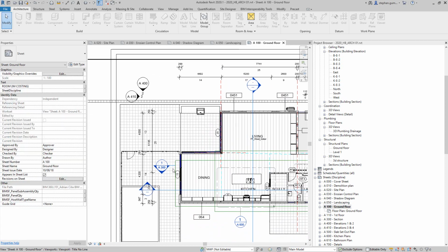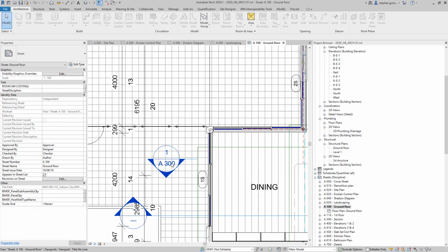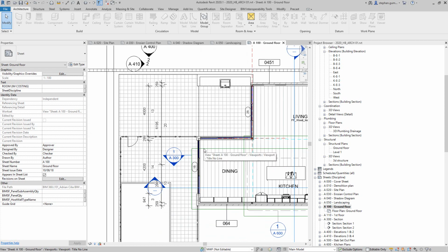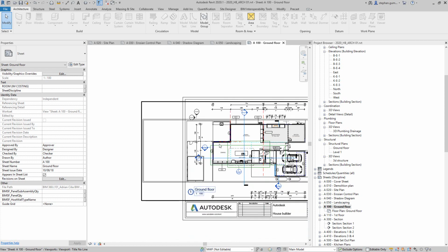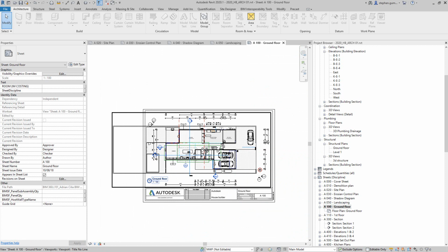And in the cases where we've actually dragged the sections onto a drawing, the section numbers automatically correlate to the actual drawing themselves. So you can see section 1 is on A300. If we go to sections A1300, you can see section 1 is here. If this drawing was to change number, this section number would change, and so on. The intelligence or the connection between all the objects is a whole lot different, giving you more control over your design because there's less things you need to worry about.